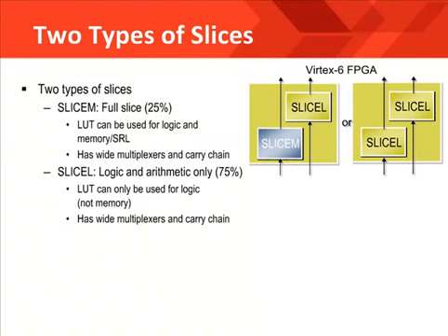The rest of the slices are SLICEL, which are logic and arithmetic functionality only. So the LUT can only be used for logic. There's no distributed memory resource there. It also has wide multiplexers, and of course the carry chain is associated with it.